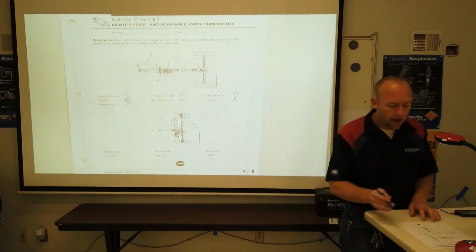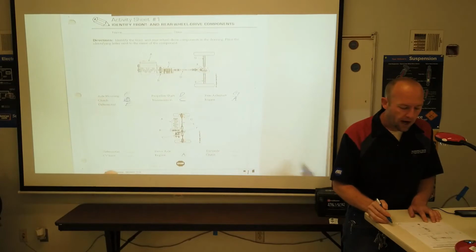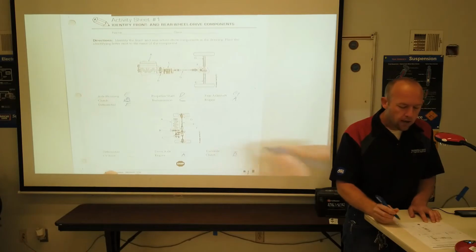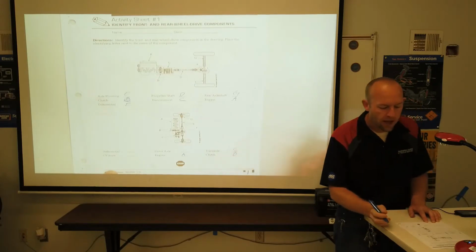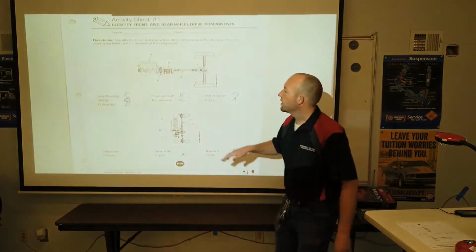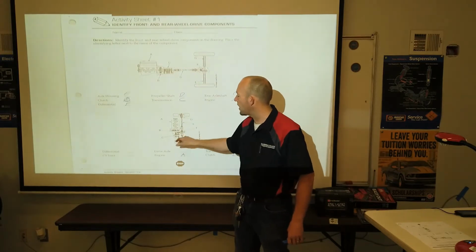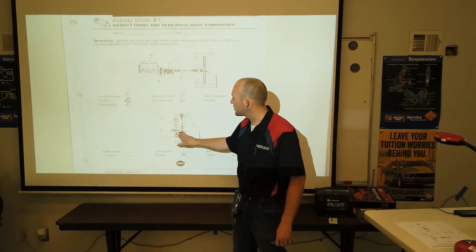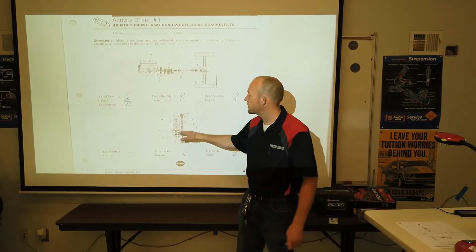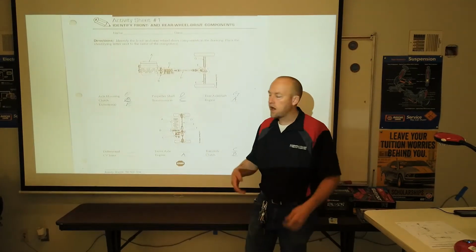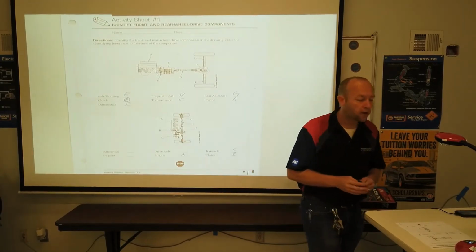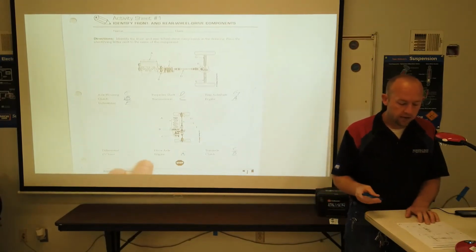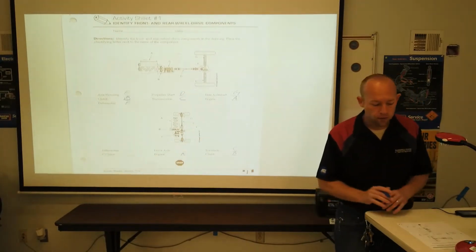So moving on, A is still the engine, and B is still the clutch, but C is now something different. C is referred to as a transaxle. What they've done is combine the transmission and the differential into one housing. You can see those: there's our transmission, there's the differential. This is still a manual transmission since it has a clutch. But what did they get rid of when they combined that transmission and differential? The propeller shaft, or the drive shaft, or drive line. That gets eliminated on a front wheel drive configuration.